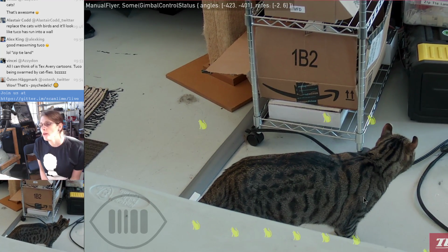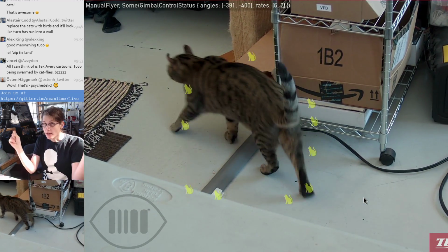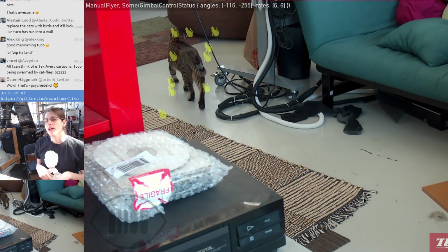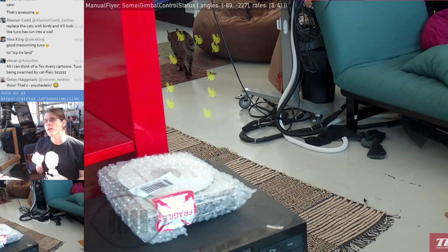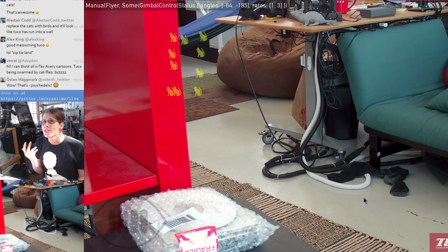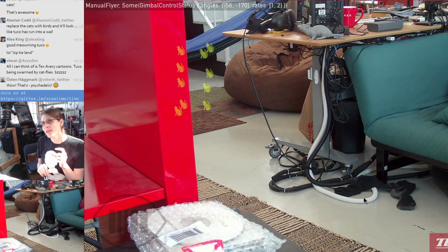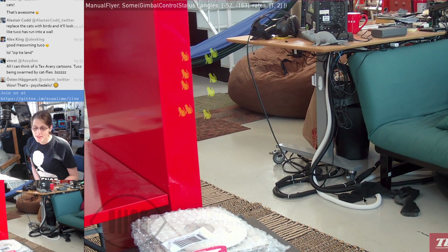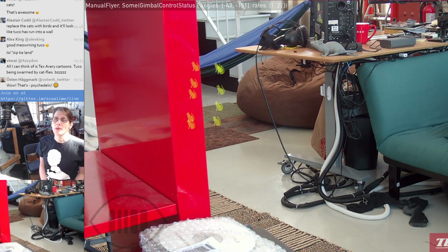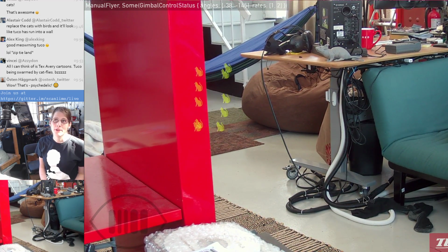So the current strategy overlaps that rectangle with some rectangles at the edges of the screen that define gain regions. Each rectangle has an XY width height, and it has a 2-component vector which describes what nudge we should give the gimbal. All it's doing is overlapping those rectangles, taking the intersection, then taking the area of the intersection and multiplying it by the gain. It kind of sort of does the right thing, but it scales completely wrong because it turns out you don't actually want quadratically more gain when the object is that much larger in the frame.